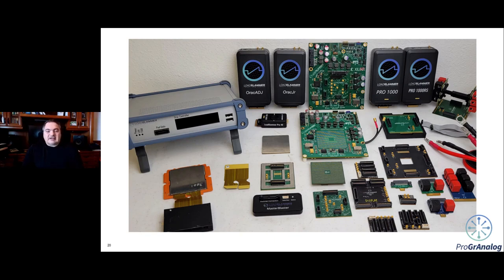Yeah, we didn't really cover telemetry at all. I apologize for that. We do have what we call the blaster, or the master blaster. It's in this picture here at the bottom, and we have most of the protocols available in the market, including the proprietary ones by AMD and Intel, and basically you can plug that blaster in and capture telemetry from a power management device, and you can also write to the power management device through that blaster. And the API ties the blaster into the GUI so that all the telemetry data is captured.